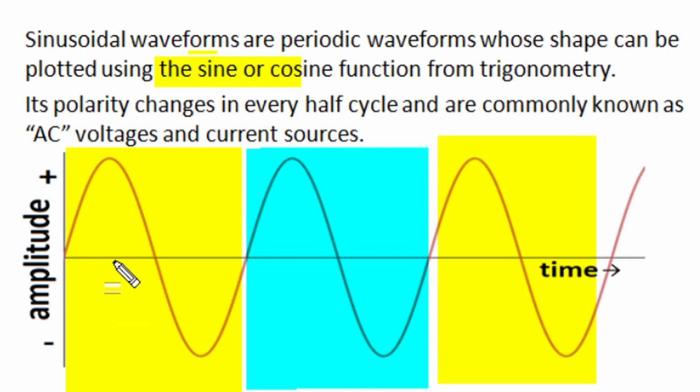And in a typical sinusoidal alternating supply, the magnitude increases at a higher rate from zero initially, and the rate of increase continuously decreases and magnitude attains positive peak. After the positive peak it decreases initially with smaller rate and then at faster rate, again attains zero level, and voltage changes its polarity and current changes its direction, and the same variation, changing polarity or direction after every half cycle, is repeated again and again.